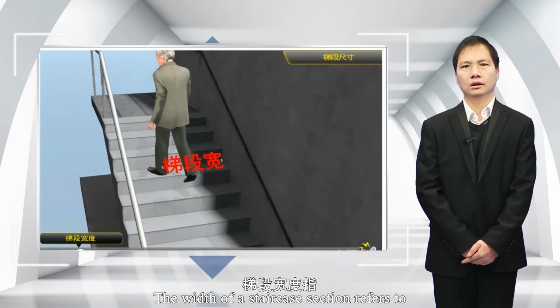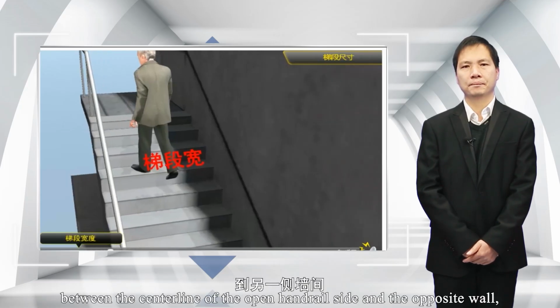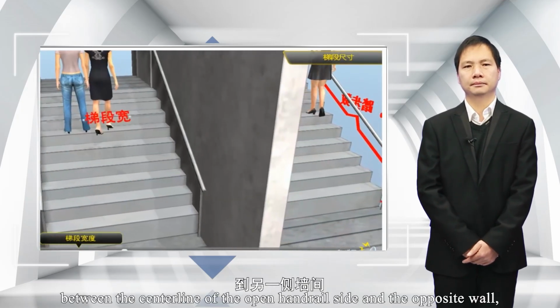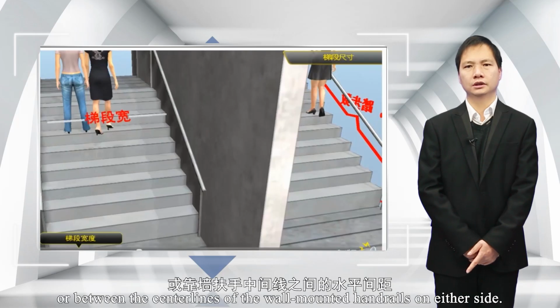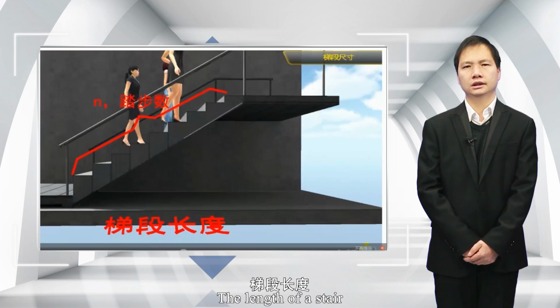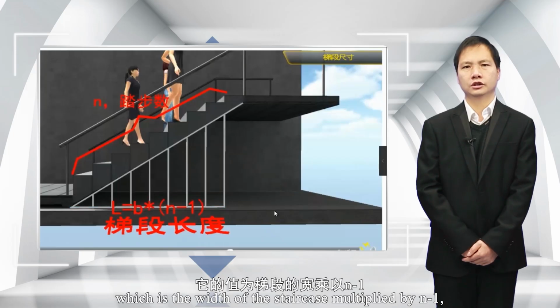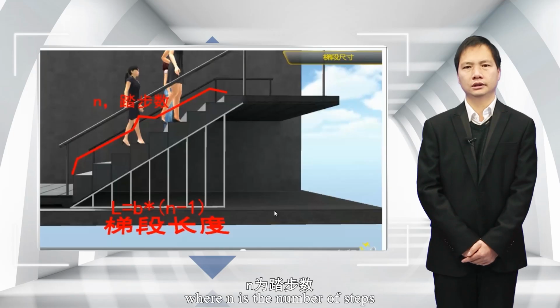The width of a staircase section refers to the horizontal distance between the center line of the open handrail side and the opposite wall, or between the center lines of the wall-mounted handrails on either side. The length of a stair refers to the horizontal projection length of a stair, which is the step width multiplied by n-1, where n is the number of steps.